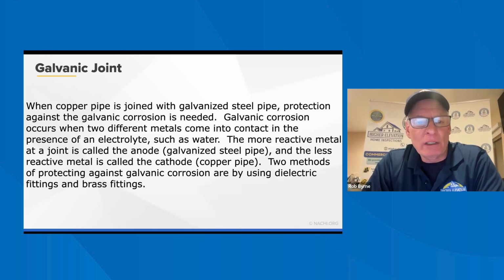So you've got to keep on turning it as opposed to a quarter of a turn on the ball valve. The gate valve, you're pushing down on a threaded piece inside, and those fail. And of course, you have the other type of valve where it seats in, and that's even a little more difficult to operate. So those, they don't really use that much as shutoffs. You do see them. The newer styles are much better, but the ball valve is pretty much, a lot of the plumbers, the go-to for them.